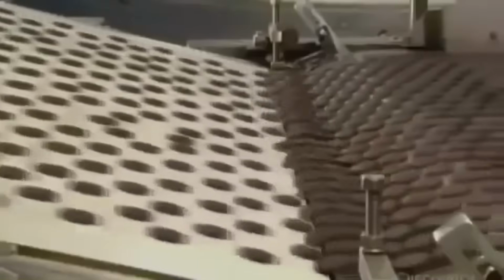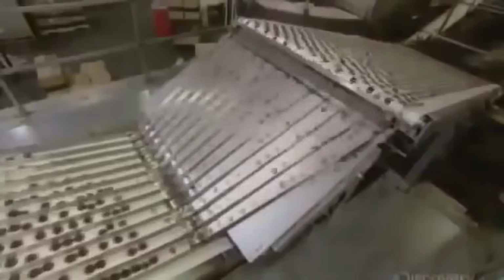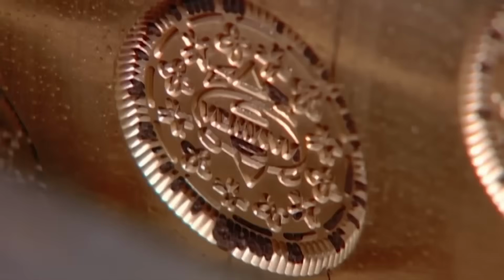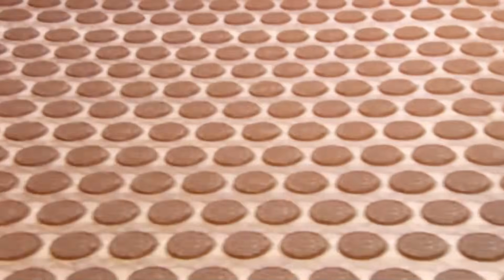Sensors measure the thickness of the sheet continuously using laser or ultrasonic gauges. If deviations are detected, servo-driven actuators automatically adjust roller spacing to maintain precision. The sheeter also includes edge trimmers, small, motorized blades that cut off uneven or frayed edges of the dough sheet to keep the line uniform. The trimmed edges are collected by a scrap recovery system and reintroduced into the mixing system, minimizing waste without compromising freshness or quality. Once the dough sheet is perfected, it enters the rotary molder.